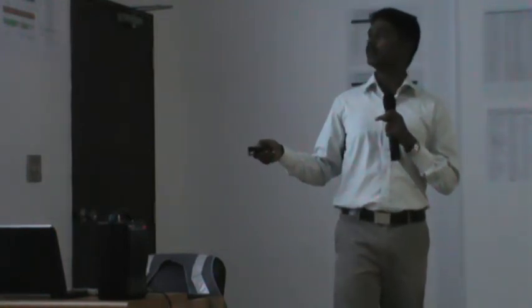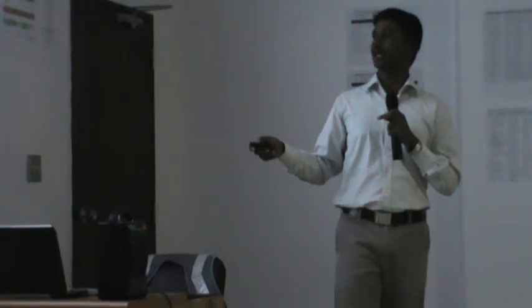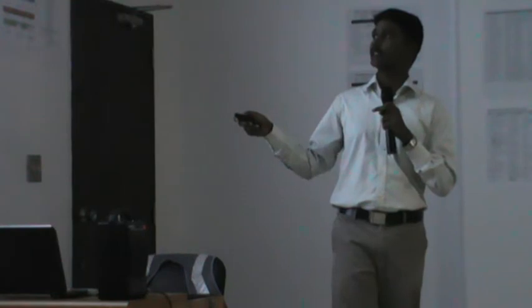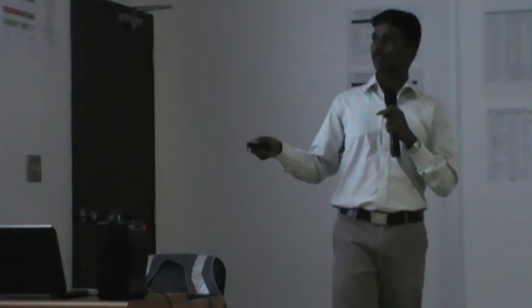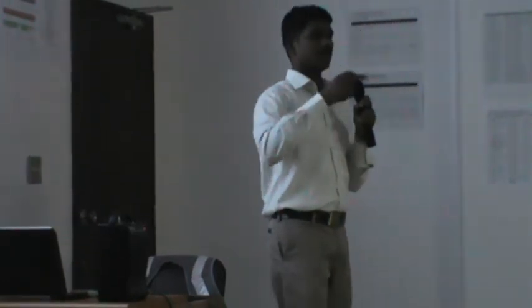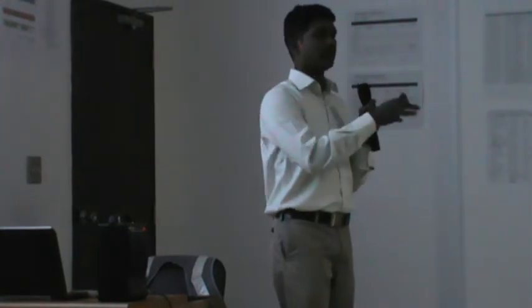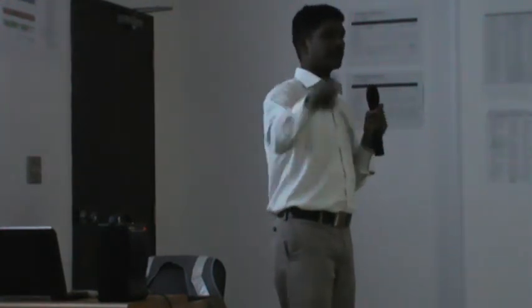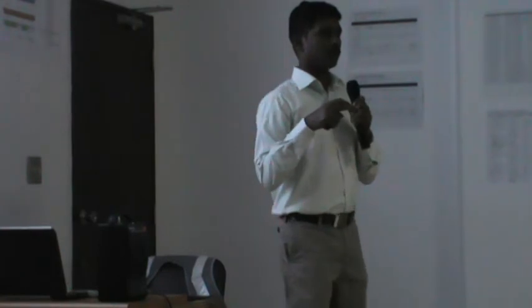I can show. So like this, this is the cabinet in the DCS, and the cable will go to the field and again it will come back to the DCS. So it is like a loop. You can get the redundancy also in this manner. If something happens to the cable at one end, it still can communicate from the other end. So that kind of configuration is available.